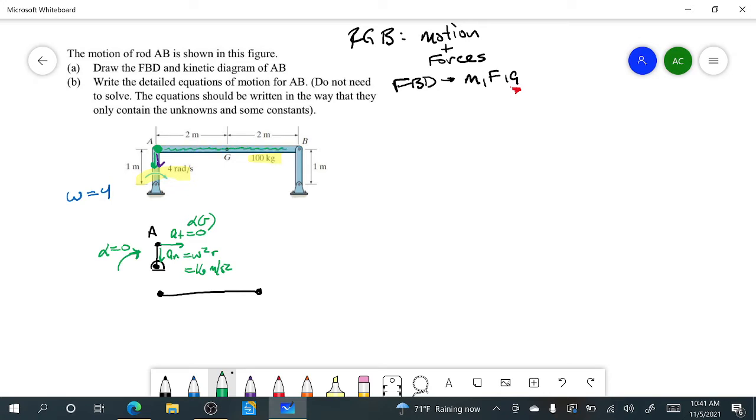This zero tangential acceleration, since it's perpendicular, is going to go straight across. And because of the way that the problem is drawn, because of the symmetry, that means that AB tangential is also going to be 0, because tangential acceleration travels along arms and it travels along wires. And so the same exact thing is going to happen to AB, because AB has the same distance and it's in the same orientation. So I could draw my arm to B. I know that the tangential is going to be 0 because it travels along just like that.